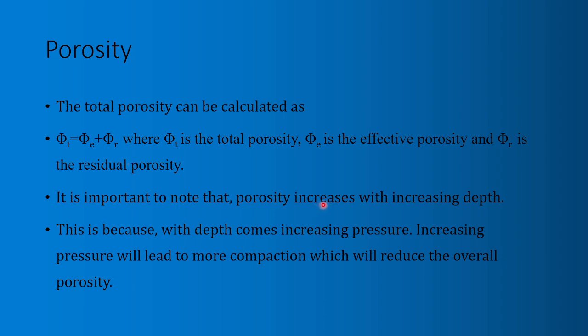And one important thing to note is that porosity decreases with increasing depth, because as we are increasing pressure, we are going to reduce the overall porosity. When we increase the pressure of the structure, we are making it more compact. We are pushing the structure together. And so the amount of pore space that's available will reduce. So it was supposed to be porosity decreases with increasing depth.